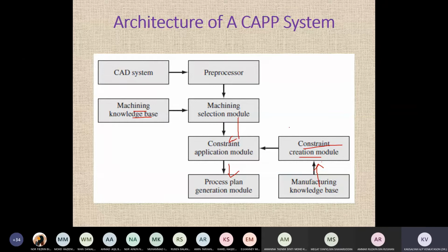Then there is a constraint of the type of plastic material that you need to use for the specific type of machining. So now let's say we are embarking on trying to injection mold recyclable plastic waste materials, okay. So these recyclable plastic materials could be a mixture of compositions, not necessarily PP or ABS, all right. It may not be polypropylene, it may not be specifically ABS, maybe a combination of all, including contaminants, maybe, because we are recycling and crushing the entire plastic, right?